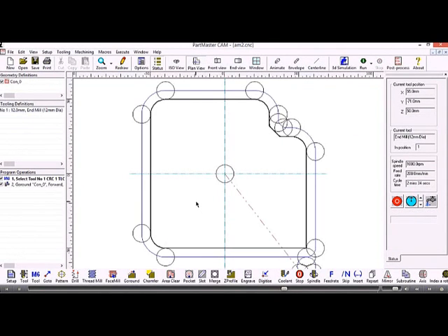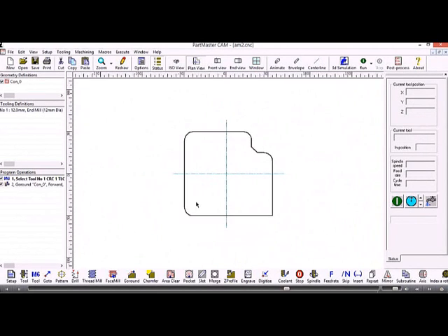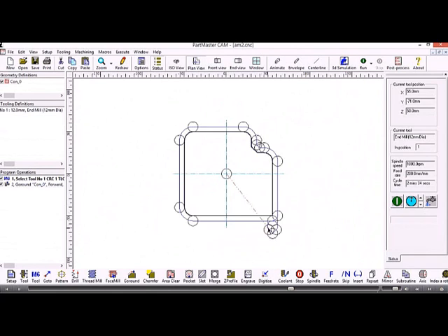So that's showing me the toolpath on the screen. If I just use the mouse wheel to zoom in and out, the tool starts off at its home position, which is 0. It rapids to the first position here, shown by that dotted red line, and then goes down to the depth. The blue line is the center of the tool.